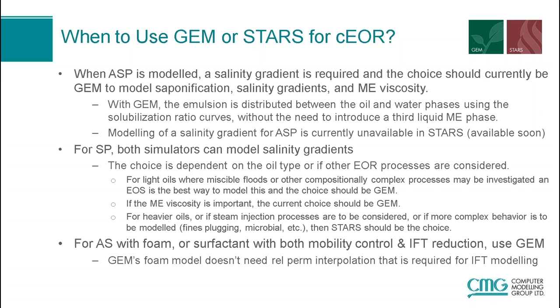For surfactant polymer or surfactant with foaming capabilities, both simulators can model salinity gradients. So then the choice becomes dependent on the oil type, or if there are other EOR processes to be considered and compared. Now, for light oils, where miscible floods or other compositionally complex processes may be investigated, an equation of state is the best way to model this, and the choice should be GEM. If the microemulsion viscosity is important, then the choice should be GEM.